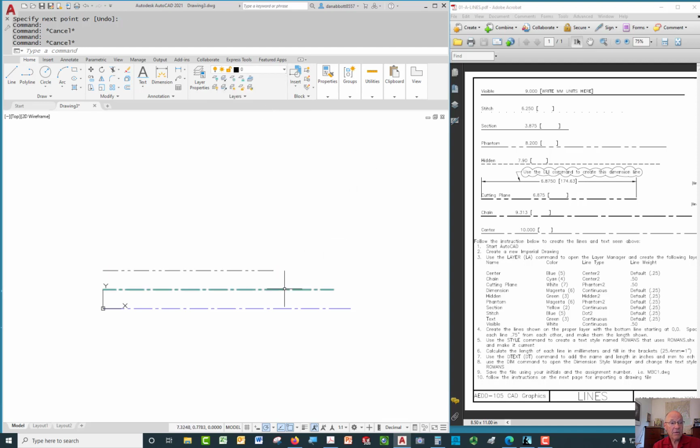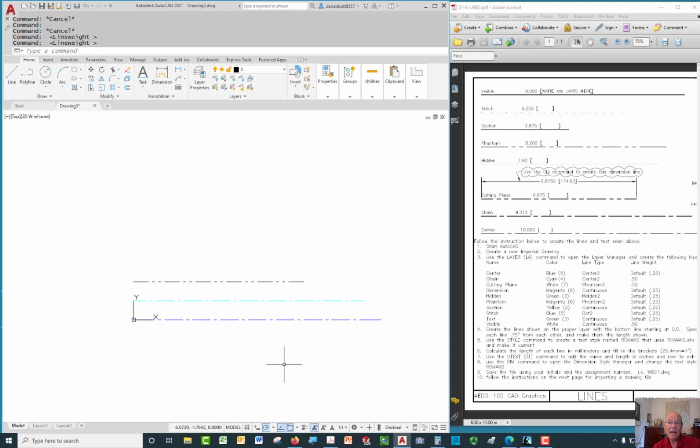Now these line types are correct, but the line weights aren't showing yet, and that's because I haven't turned line weight on. Most people, when they work in AutoCAD, work with the line weights turned off, so all the lines are thin. What I'm going to do is turn the line weights on, and you can see that I have 2 thick lines, 1 thin line. Now I'll turn it back off. Once again, before I pause the video though, let me put a dimension in here.